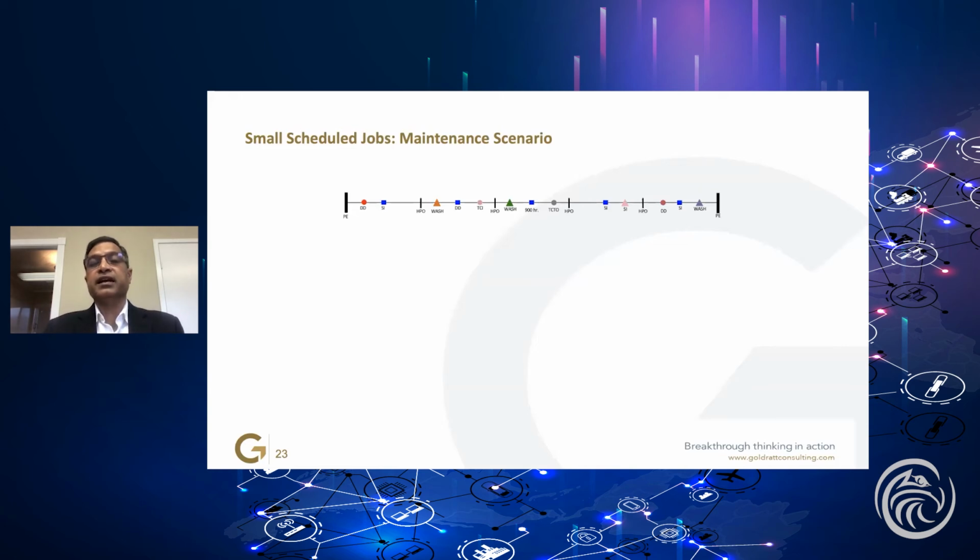If you take a single aircraft and you look at this line, think of it like a timeline. At the 2 extremes are the 2 PEs or the 2 ISOs that's done once in 2 years. And then along the time, you do a whole bunch of inspections along the way. Some of them are very small, half an hour, an hour. Some of them are a few days. But that's what every aircraft goes through. And each of these inspections falls due at a certain time interval or an hour interval or a cycle interval, and it will vary from aircraft to aircraft.